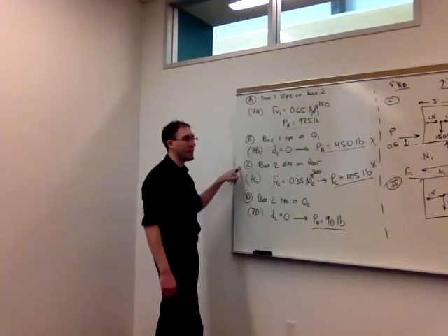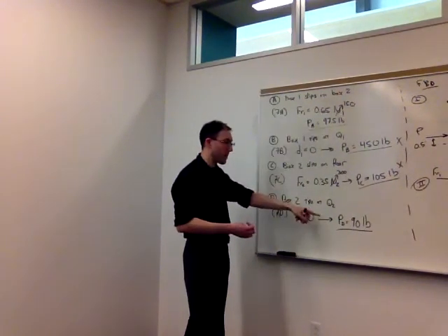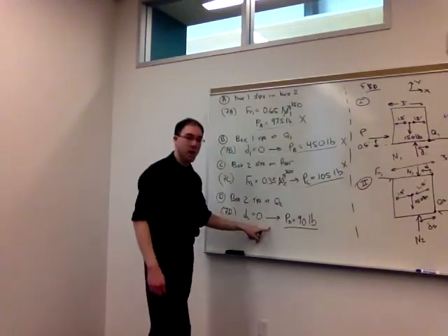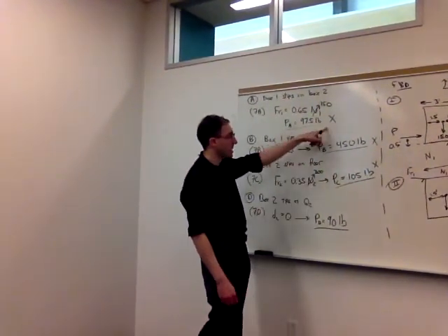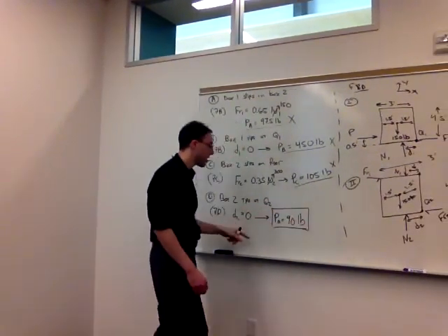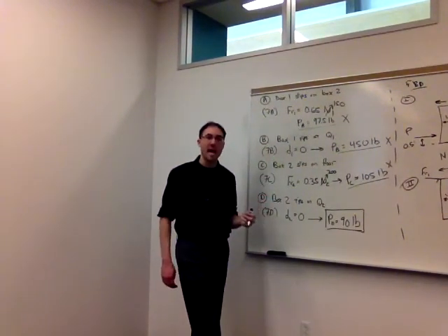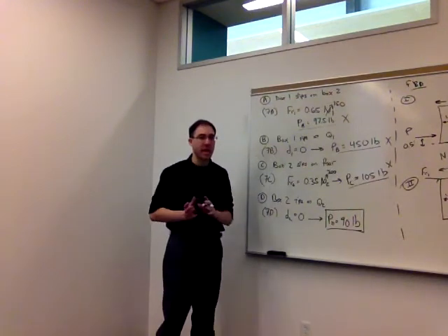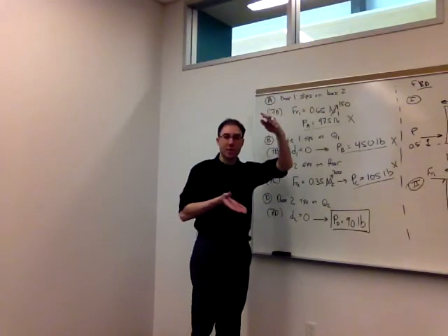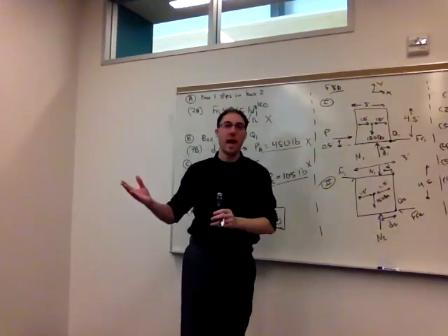We've eliminated B, we've eliminated C. This is less than A. We're looking for the smallest force here because that means it's the hardest we can push. So now A can't happen because it would already be tipping at D by the time the top would slide relative to the bottom. So the smallest value here, the minimum of this, is the maximum that we could push before there would be any motion in the system. And we would say that the first thing that would happen is once we get to 90 pounds, the two boxes together would start to tip at that bottom corner, Q2, or in that picture, B.